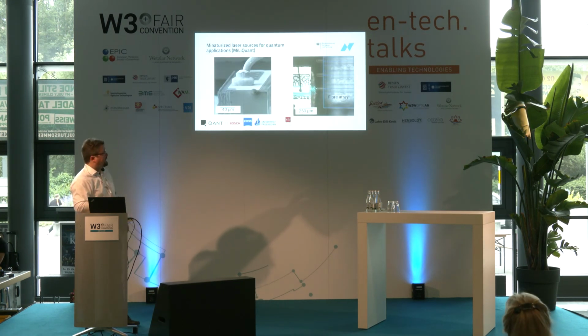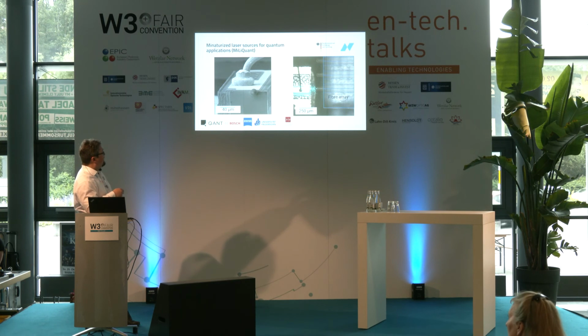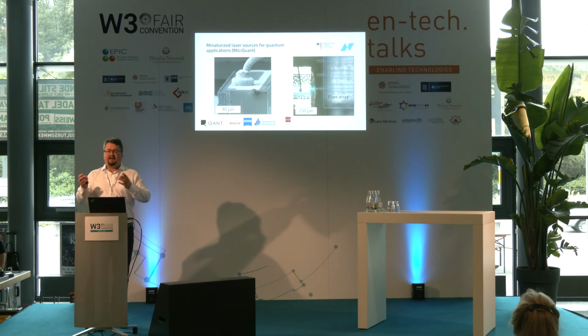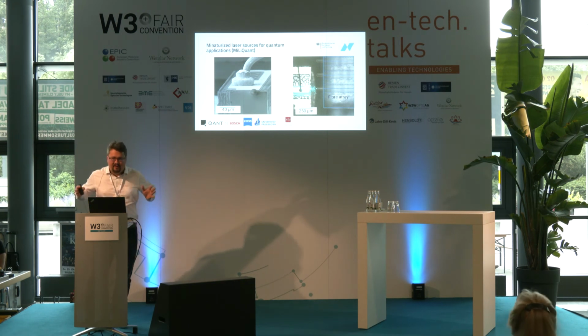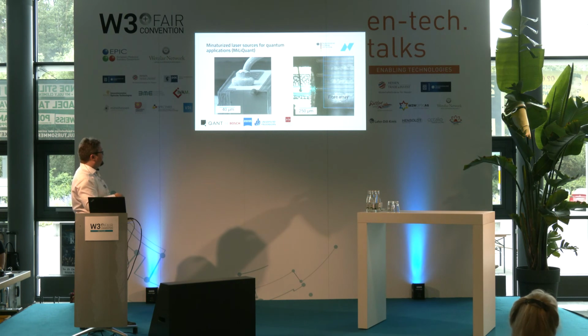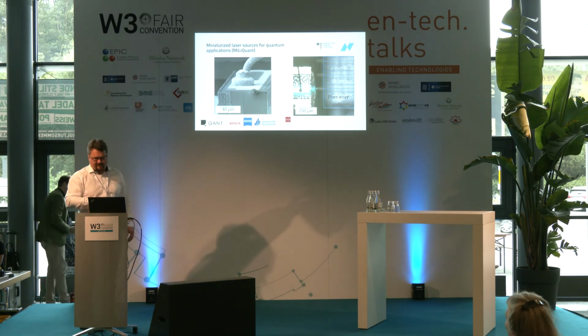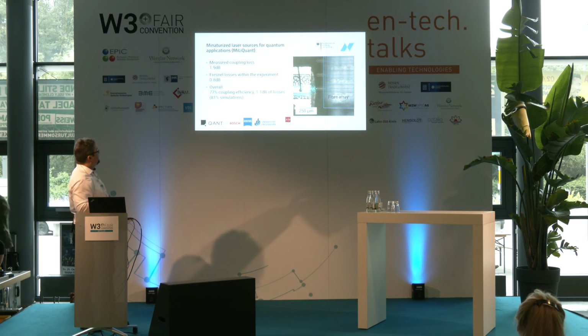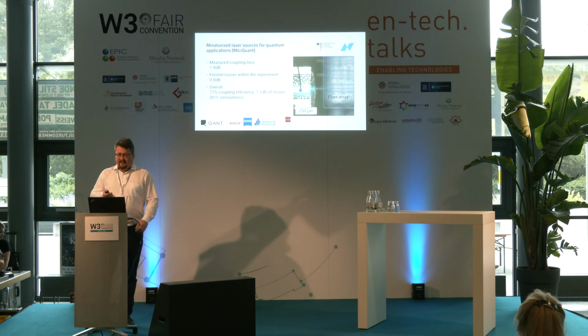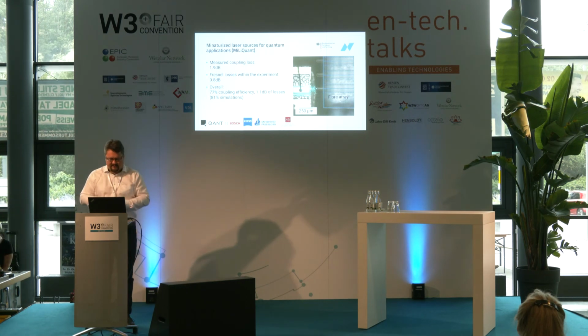So we're also participating, I mentioned this before, in the milliquant project for light sources, and here you can see a printed lens actually on the exit of a laser chip that has been fully electrically contacted. So now you can actually get the light that's generated in your laser chip focused and in the direction that you need it to go. Or we also looked at a fiber array to couple from the chip into the array, and we also characterized this setup and got fairly good results. If you're interested in those numbers, talk to me afterwards, I would say.